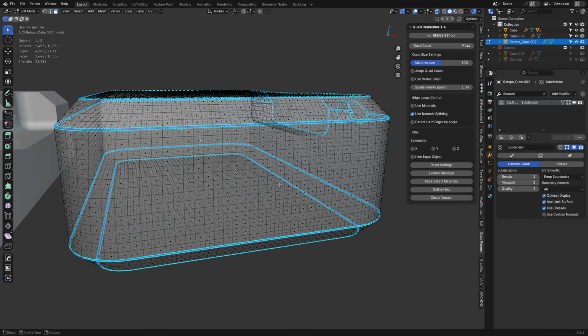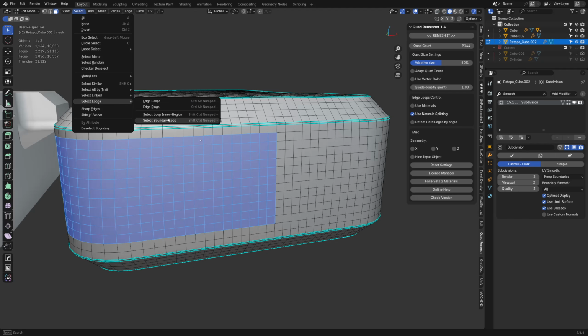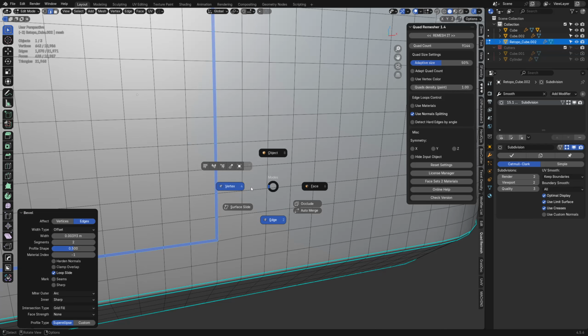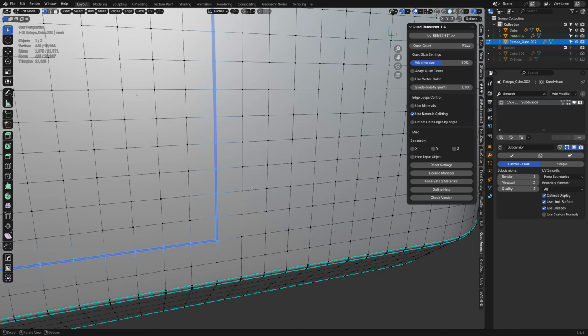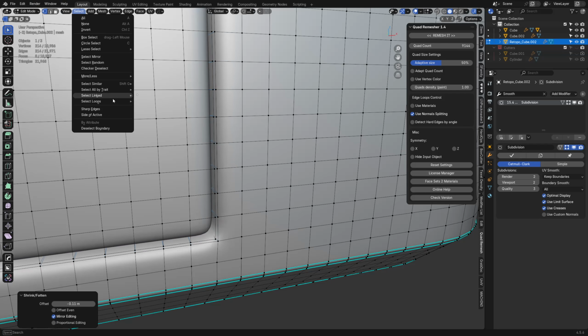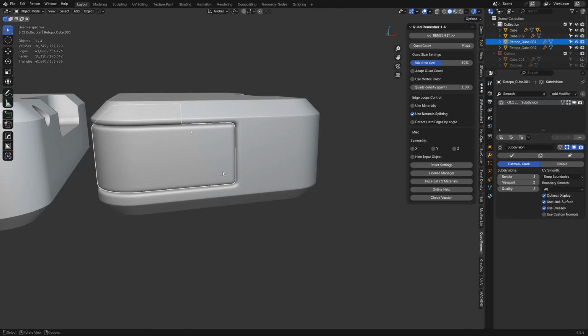actually, before we go that far, let's do select loops, boundary loops. Right here, I'm going to bevel this a tiny bit. Mouse wheel up once, switch to vertex selection, Control Numpad minus, select less, Alt-S, you can bring that in. Now you can do select loops. Instead of doing boundary loop, do loop inner region. P, separate selection. There you go. You got 2 objects now, right?